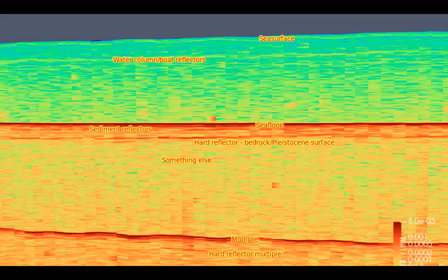That's really the meat and potatoes of the sub-bottom profiling interpretation, in regions like this, is really being able to pick up that sort of hard reflector that may correspond to the bedrock or consolidated material underneath the softer marine sediments above. Now, I won't overinterpret this anymore at this point. It's not actually terribly much going on in this section, but this is a standard example of the sort of data you get. Sometimes it's interesting, sometimes it's not, but this is the basic start of interpretation for you guys, the things to look out for from the geophysics point of view. The rest is really then up to putting this in an environment where you can start interpreting the geology, and that's what we'll be doing in the practical today.